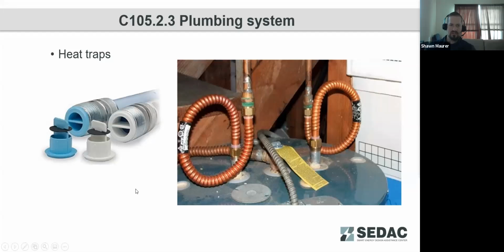And for hot water storage tanks, you do need to have heat traps installed. The picture on the left here is what those might look like before they're actually attached to the system. On the right, you see a different method where you've got kind of a heat trap loop. As hot water tries to rise through that loop, cold water has settled in the bottom end and prevents water from circulating out under natural convective forces through hot water buoyancy. So we're just looking to minimize that heat loss coming out of those storage tanks from natural circulation loops.